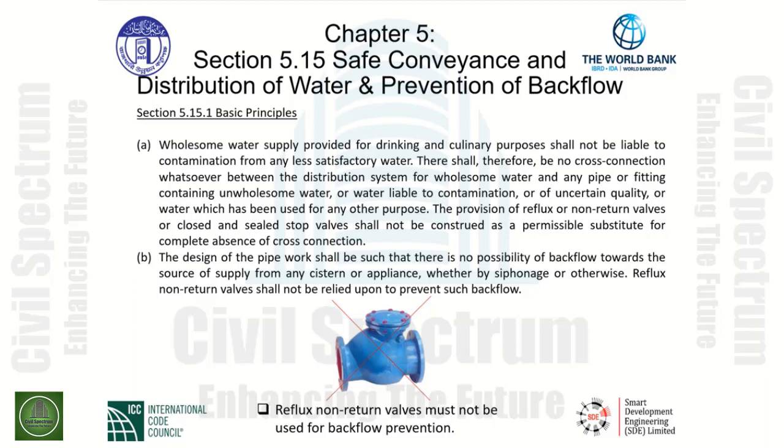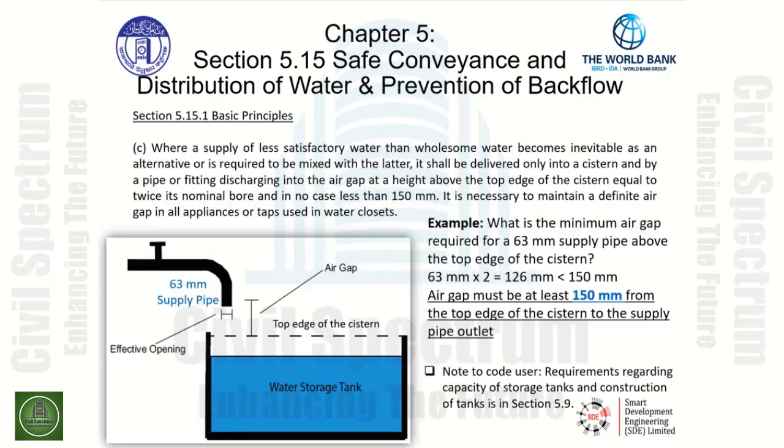Even in backflow situations where we have pressure differentials, where unwholesome water may flow back towards the potable water supply, we will not rely on these valves such as non-return valves. They cannot be relied upon to prevent such backflow. There are particular devices and assemblies to prevent backflow that we will talk about a little bit later. This gives us the general requirements regarding basic principles.